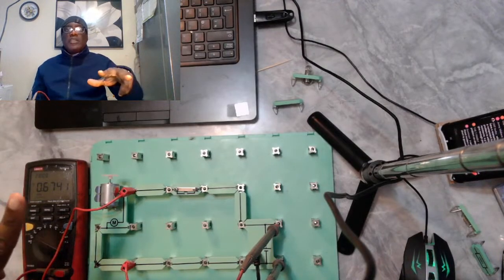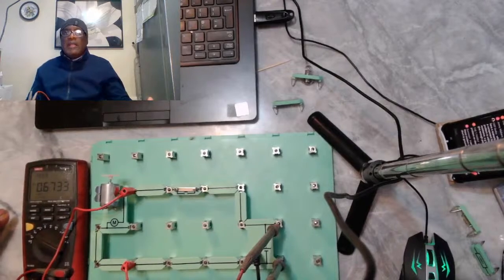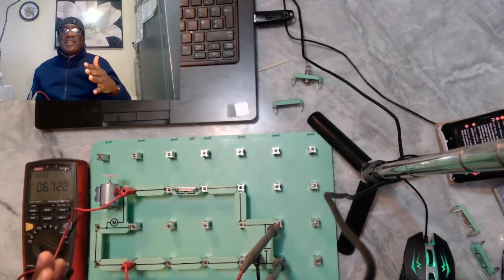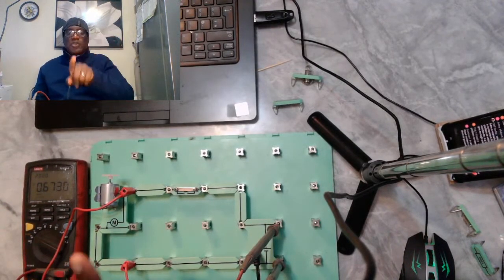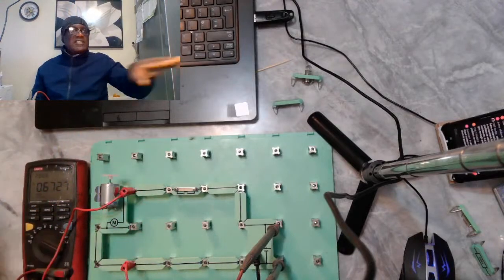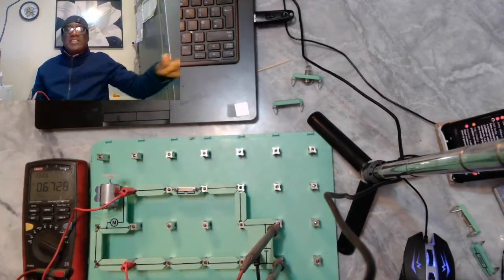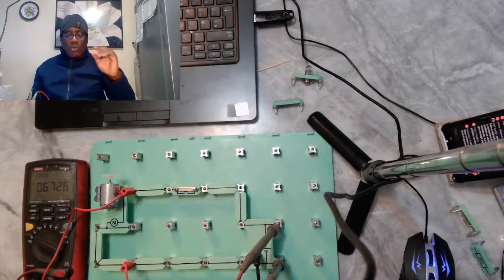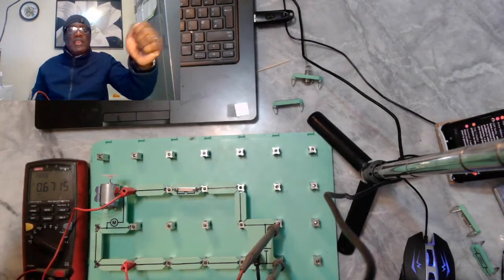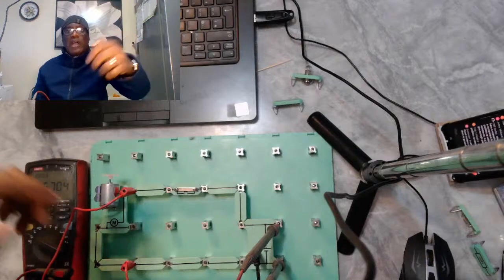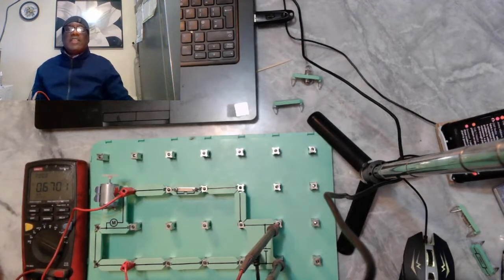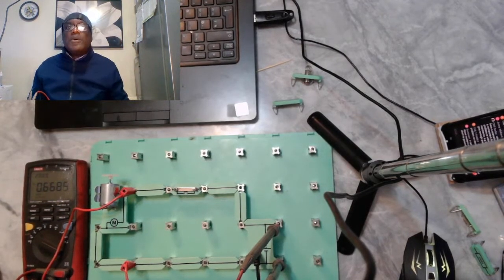It will show you what is connected inside the ECU. Yes, you have one 5-volt reference coming out, but it's actually being sent to so many sensors. Once you have that knowledge, you just go in and pull out the one that has an issue, bingo.